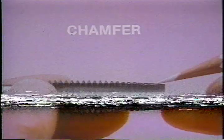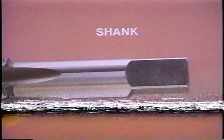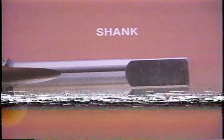The leading side of the land is called the cutting face, and this face is responsible for the proper cutting action of the tap. The chamfer is the angular slope at the front end of the tap. This taper allows the tap to gradually cut deeper and deeper threads until they are completely formed. At the opposite end of the tap is the shank.